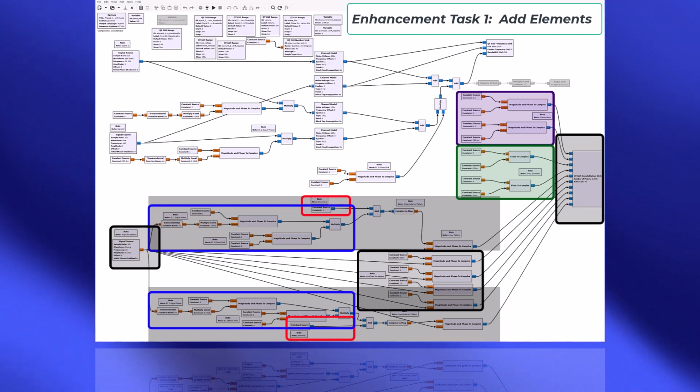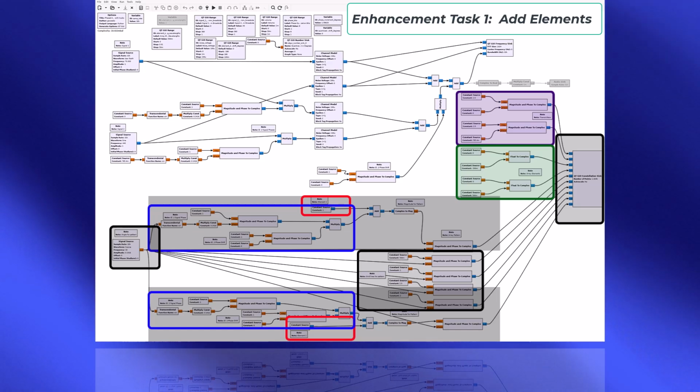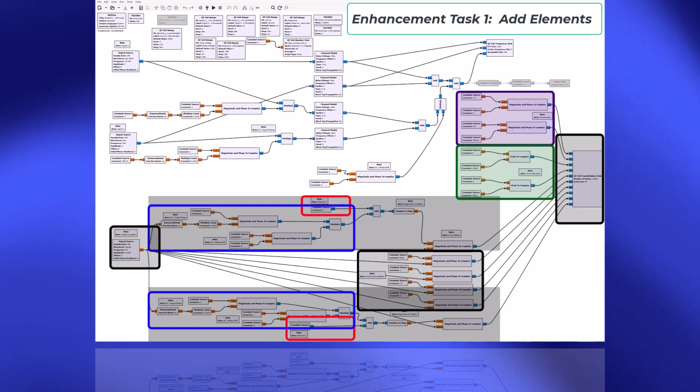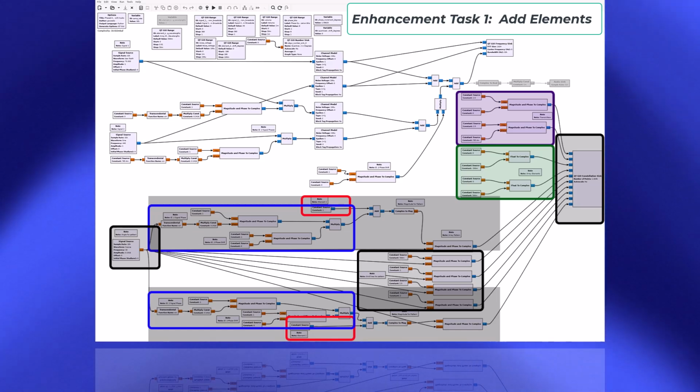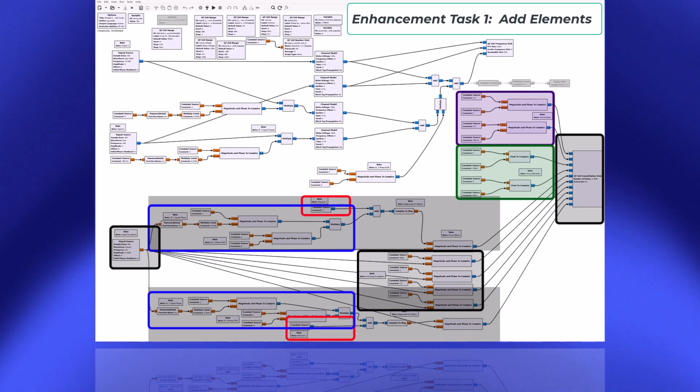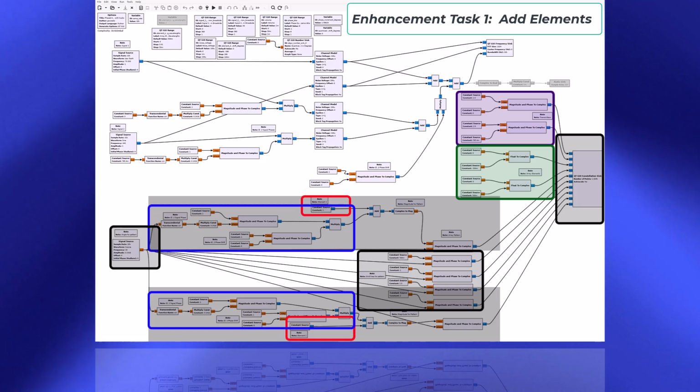And as that cosine signal goes through that range of values that correspond to a range of angles, we use that as the phase input for a complex number, and we take the magnitude that we calculate that also corresponds to the phase from the signal generator. So we use that cosine signal as a phase reference.